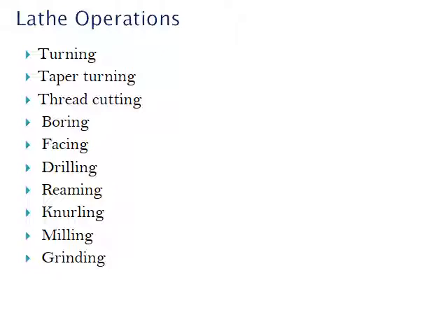For the swivelling compound rest method, there is a simple formula: tan theta is equal to (D minus d) divided by 2L. Then you can get the angle theta. According to the dimensions given in the drawing, it may be 6 degrees or 7 degrees, and you have to calculate the angle theta. Once you calculate the theta value, you can set the compound rest to the same degree, for example 8 degrees, then start the work, and the taper will be produced. Clear this point. Now, how to put the data in that formula.